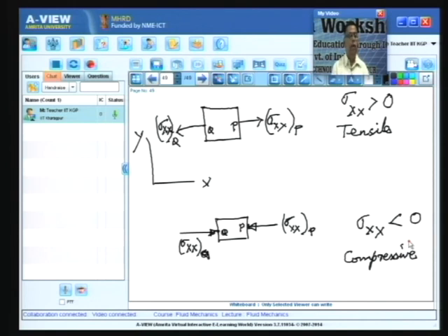Now, as I mentioned, there are many features of solid mechanics and fluid mechanics which are common. The concept of stress is similar in any continuum material, whether it is a solid or a fluid, but when the fluid is at rest you cannot have a tensile stress. The stresses are always compressive, whereas for a solid it can be either positive or negative. So, it could be either tensile or compressive.